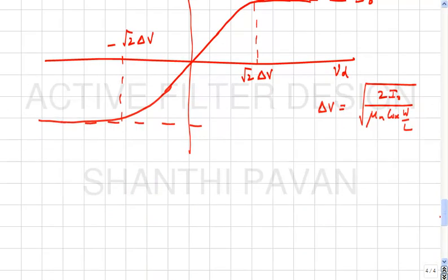Yes, a common mode will have even harmonics. And when there is mismatch between the two halves, what do you think will happen? The cancellation of even harmonics is not exact, or not perfect, but you live with it. Cancelling off 90% of the second harmonic is certainly better than not cancelling off 90% of the second harmonic. That's all, right? So you can't be worse off than the basic circuit itself. All right.